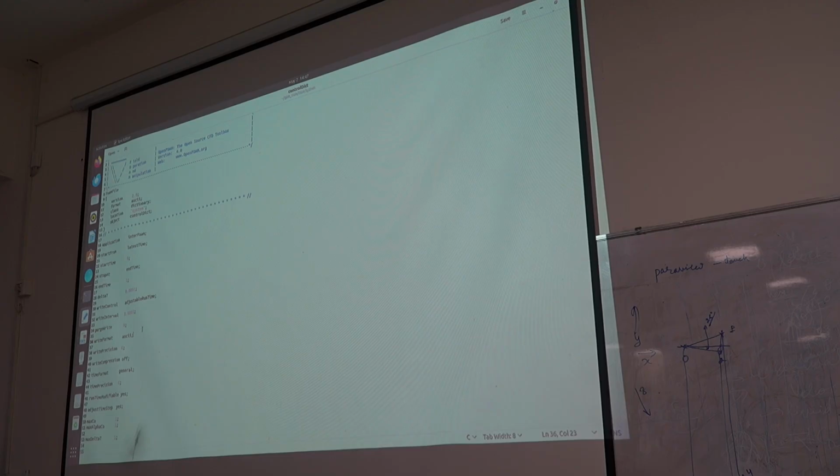Write precision 6, all the CFL numbers are 1, and during the runtime we are allowing the time step to be modified, and the CFL number for both the momentum equation and the advection equation of volume fraction is 1, and at the end the maximum value of deltaT is 1. So even if the CFL condition, because of the adjustable runtime option, gives you a very large time step, we are restricting it so that it should not cross 1 second. So this is the final thing which we were supposed to do.